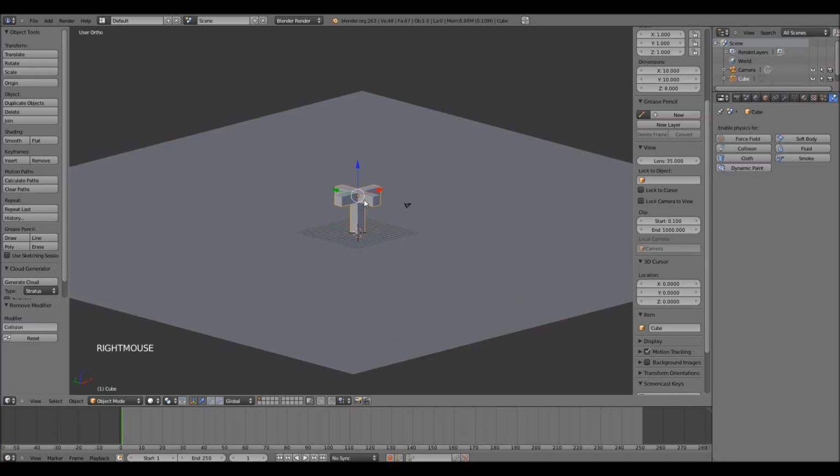Now let's right click on the object and set collision for it. So press the collision button, and then since the object will be rotating, I would like to have my particles jump with a little bit more energy in comparison to the floor. So let's go for less damping, and I will go for 0.7. And let's set our randomness to 0.15, and then friction the same as the floor, so 0.2 and then 0.1.